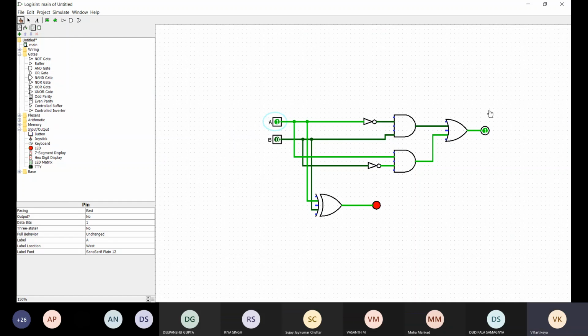So we can see that these outputs match, and for our inputs, we know that we're getting correct outputs. And for 1, 0 also we're getting the same thing, and for 1, 1 we are getting 0 again, which means our XOR gate worked. This is how you simulate stuff here.